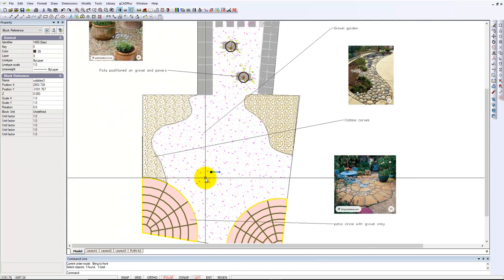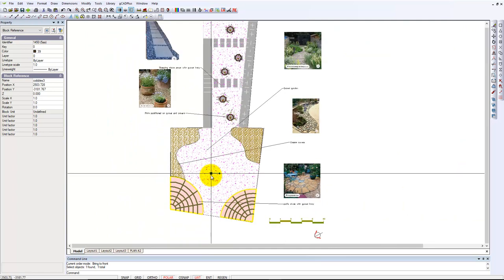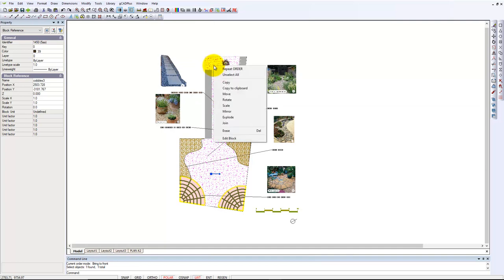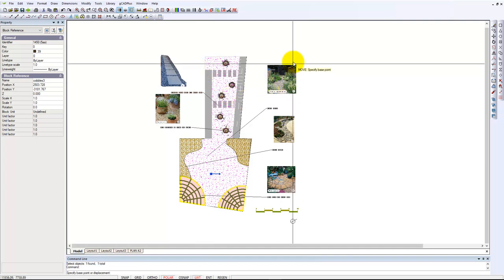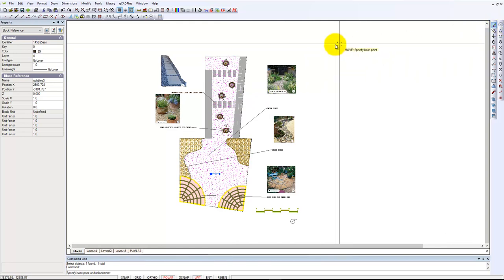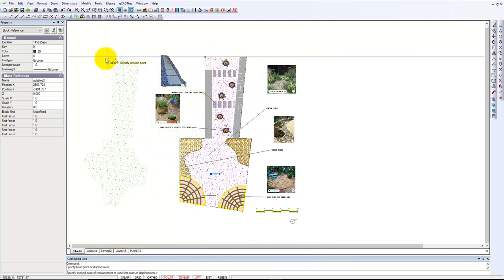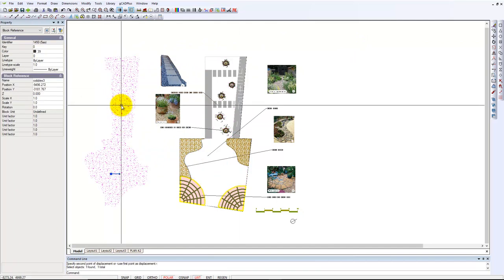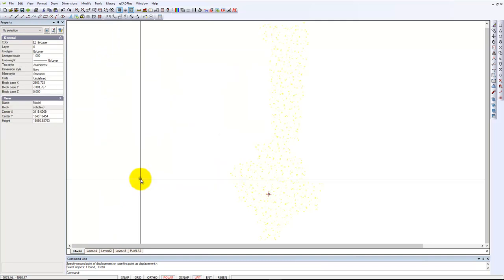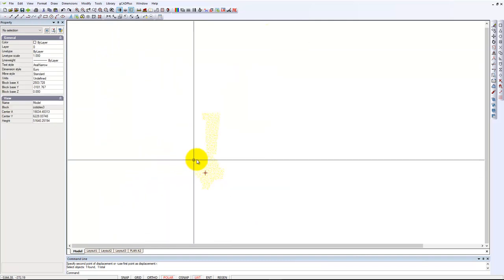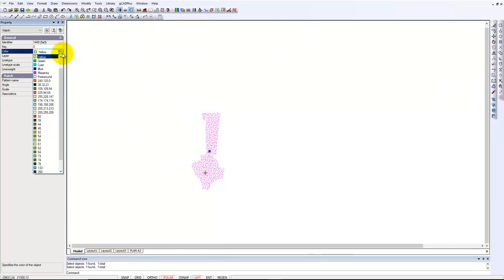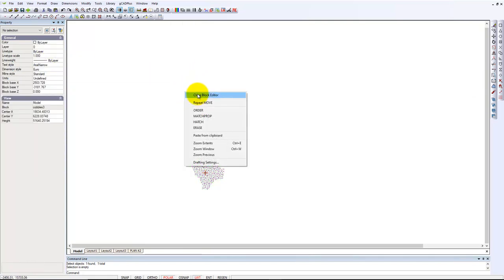It's another block. So we have exactly the same problem that we've had before. I'm going to again move, and I'll move from the end point of this one, and I'll move it across with polar on. And if I edit that block, it's been made colour yellow, so that's why we were having trouble with it. We'll just put it back to there and then close.